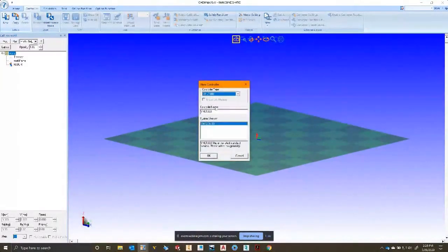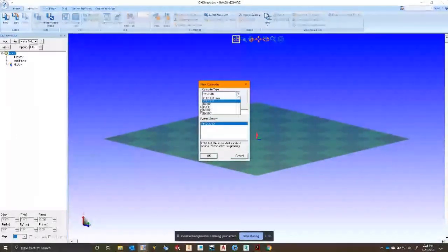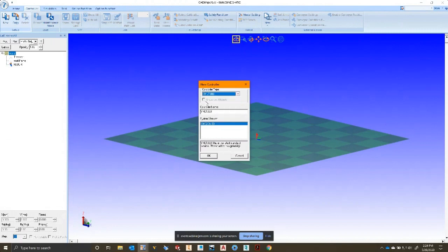We'll select OK. Now it's going to ask for a controller. So we have YRC 1000 micro, the regular YRC 1000, DX200, FS100, DX100, and DX100 controller. Our current controllers, our current robots, are going to really be under the YRC 1000 and the YRC 1000 micro. Today we'll just use the YRC 1000. Here you can give it a custom name if you would like, and this is telling you your system version, the firmware of the controller. I'll select OK.